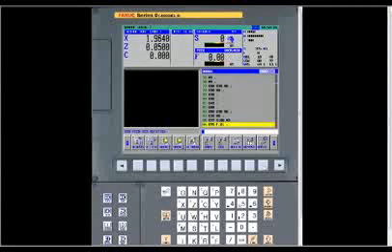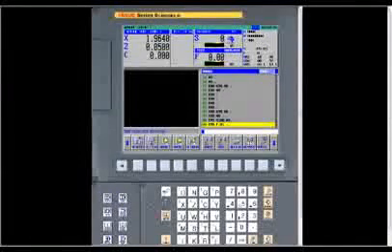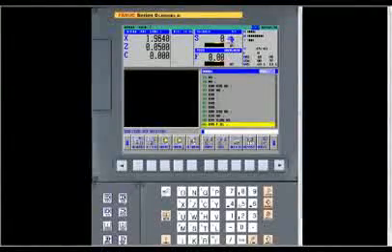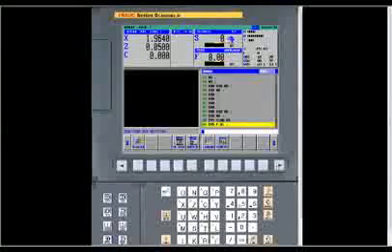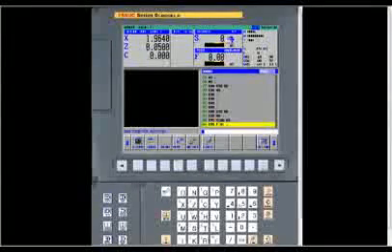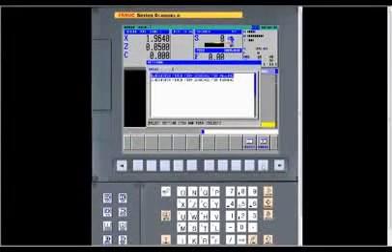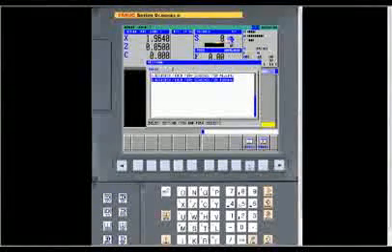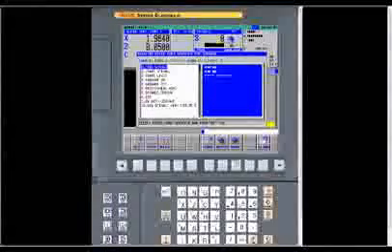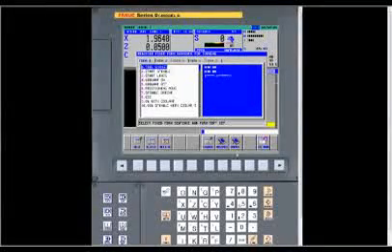Okay, good. Another question here, Jody, from our attendees: how about importing fixed forms? Yes, people ask this all the time, but you've got to get to the right screen to do it. You have to be in Edit. You go right shift until you get to a setting soft key. You press that, and you pick whichever one you want to do, register fixed form sentence for current. Then you have an input soft key.